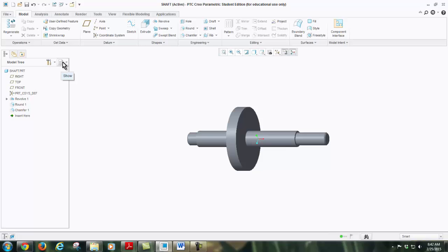And now we're going to work on changing layers. Click on Layers on the model tree. Expand Layers. Notice that the Revolve section is now showing a sketch. Now we will change layers on the model. Layers are useful for organizing the model. For example, deleting, reordering, suppressing, or resuming features. They do not affect the solid geometry of the part or object. However, suppressing a layer suppresses the geometric features contained in that layer.